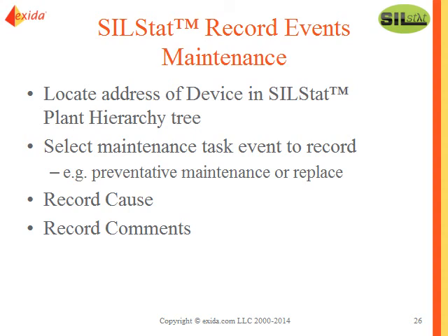You record your proof test events, and you have a record of the fact that you performed your proof test, and as you do your proof test, you have a record of whether that equipment worked as you expected, yes or no. I mentioned the maintenance activities, items like recalibration that may be required every so often, or the replacement of a part, or preventive maintenance, maybe cleaning out of impulse points. All that can be scheduled, and you can keep track of the fact that you've done those maintenance activities.